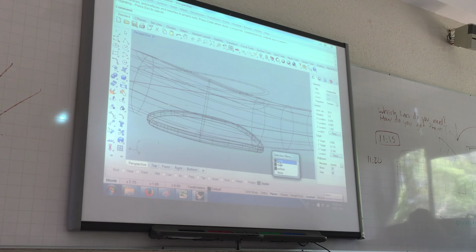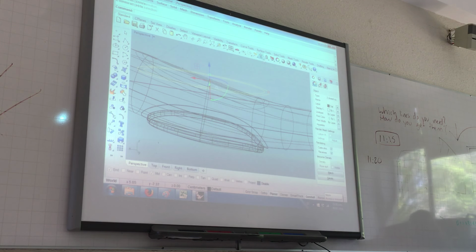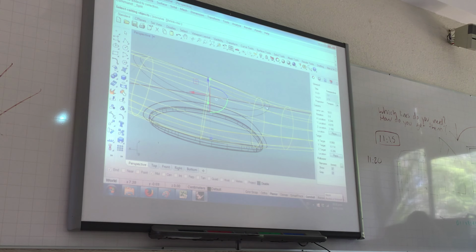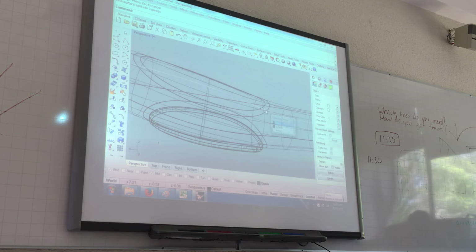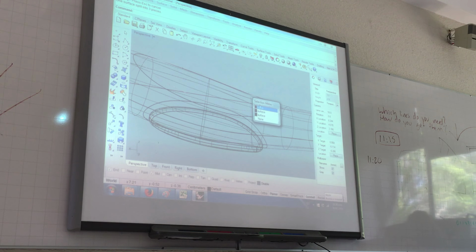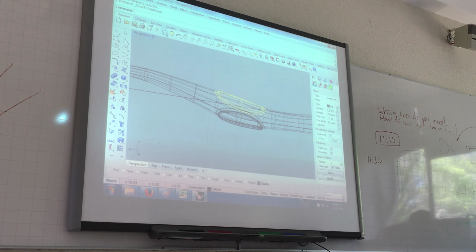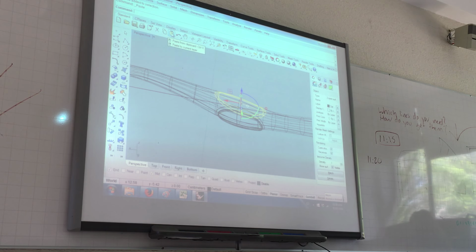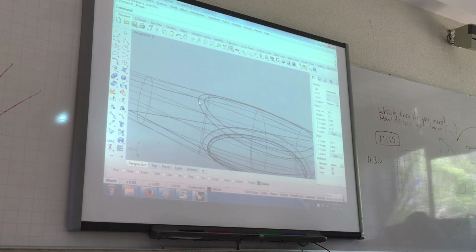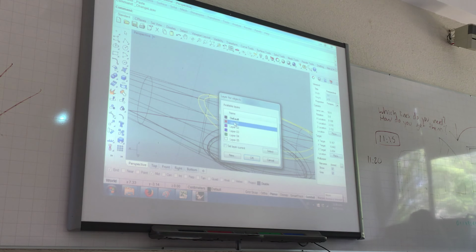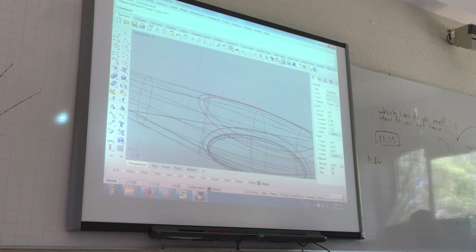I do not need this, nor the other one, nor this. I'm going to hide this too. So again, I'm going to split this object using this and this. There. So I'm going to take this surface and the other one from the second one, and I'm going to copy them to the clipboard. I'm going to undo the split. This is solid again, and I'm going to paste them, okay? Now, I'm going to move this one to a red layer just for you to see. I should have my layers with a name, but I don't want to waste time doing that.